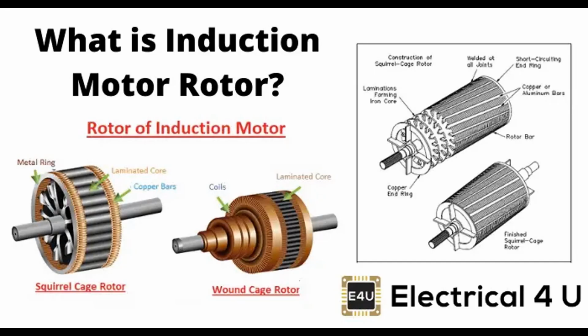Voltage regulation refers to the process of maintaining a stable and consistent output voltage from an electrical device, such as an alternator, despite changes in load conditions or other external factors. In the context of alternators, voltage regulation ensures that the output voltage remains within a specified range to provide reliable power to the vehicle's electrical systems and charge the battery. Here's how voltage regulation works in an alternator.